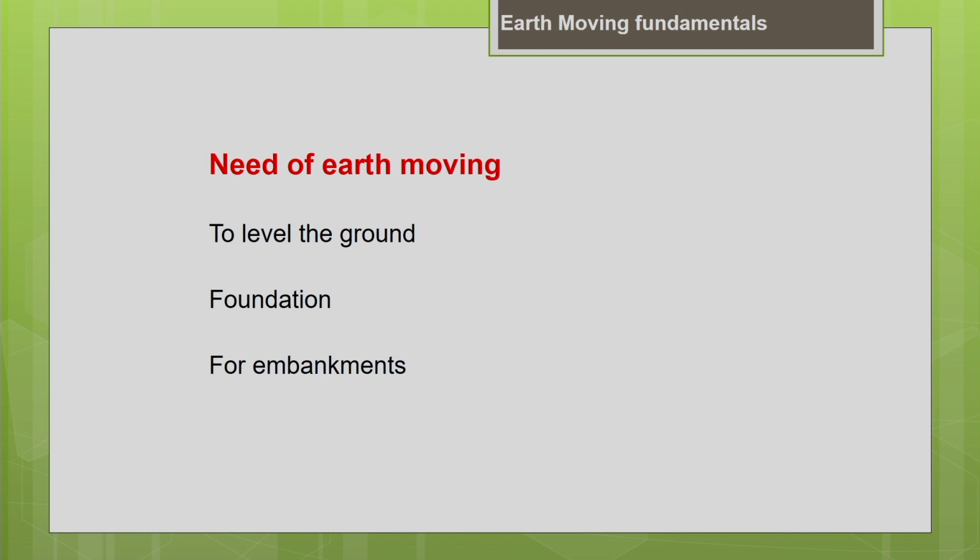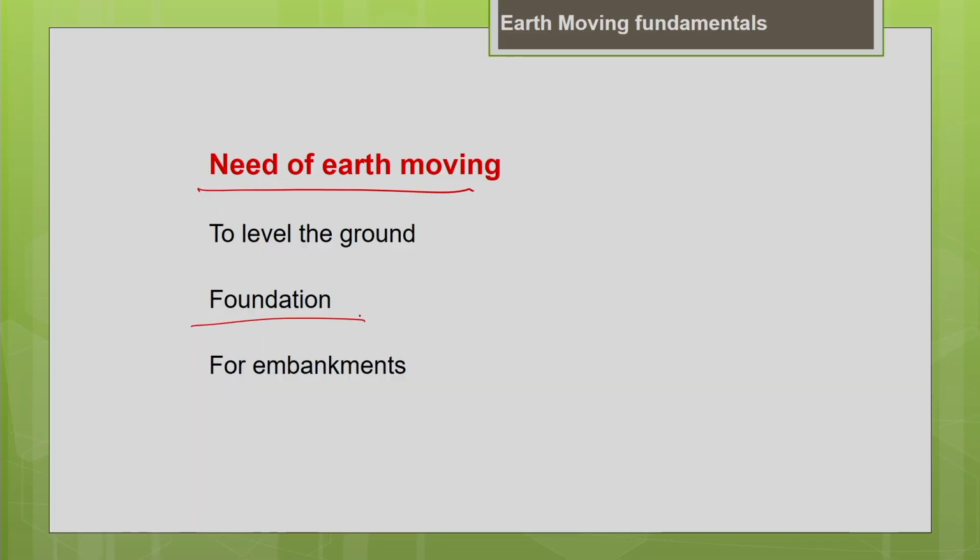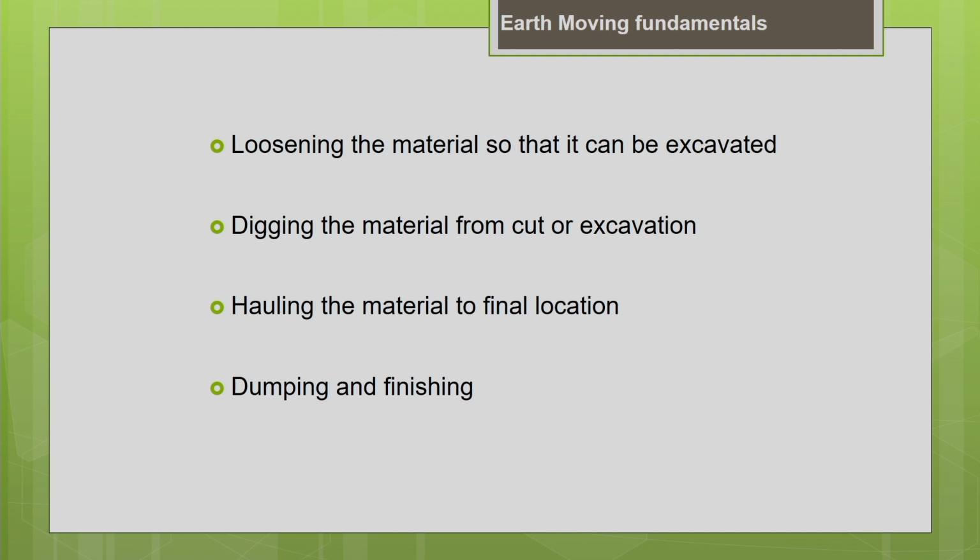So, what is the need of earth moving? Earth moving refers to a broad spectrum of construction activities. It may be simple leveling of ground, grading of ground, or stripping of the topsoil. Or it may be deep excavation for making the foundation, excavating trenches for pipe laying, or earthen embankment construction. All these involve earth moving operations. So, you can see that earth moving is a very common activity seen in most construction projects. Now, let us see the basic steps in the earth moving operation.